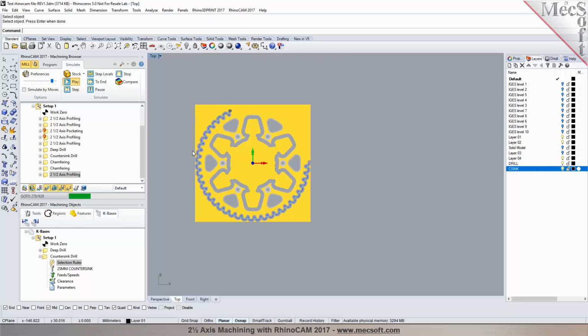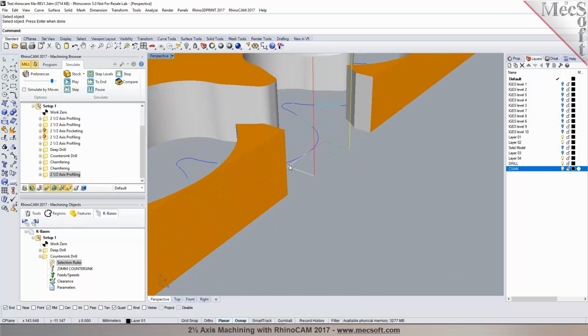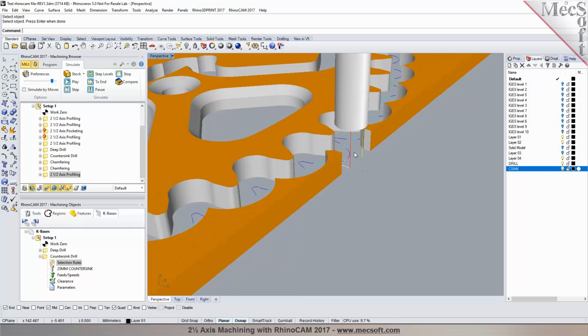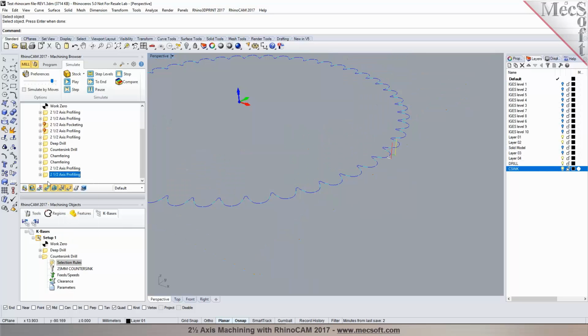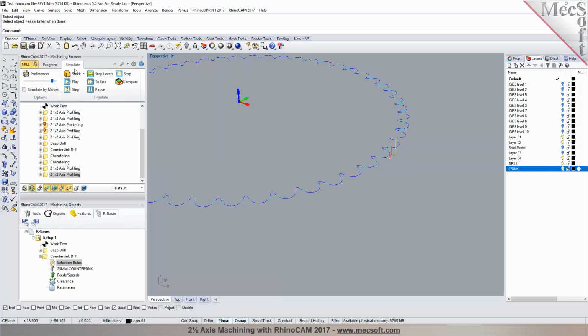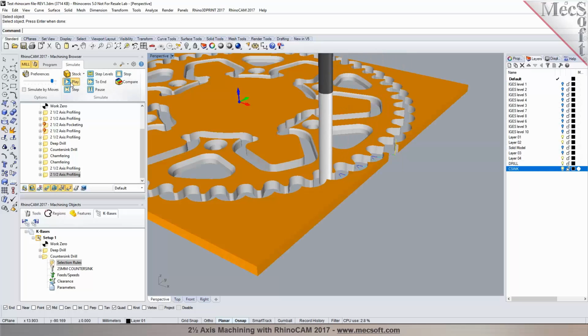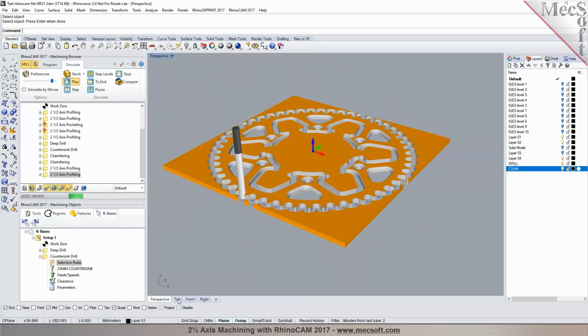As you program it. And then you can repeat the same operation over again to run a finish pass. And these parameters can be changed, the length, and I just left it at 3 millimeters. If you want to increase the length, you can always do that. So run a finish pass and make a copy, paste, modify the operation, change the stock to 0, generate. So that will give us a finish pass to go ahead and clean up the material being left.